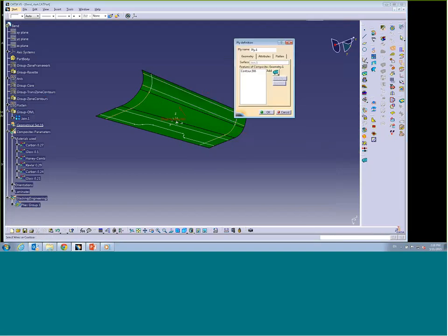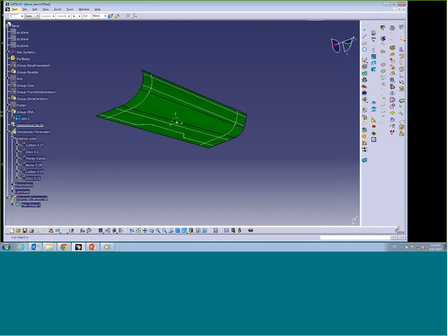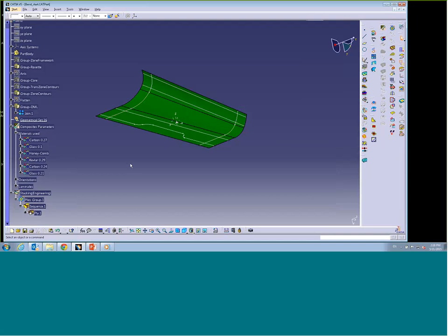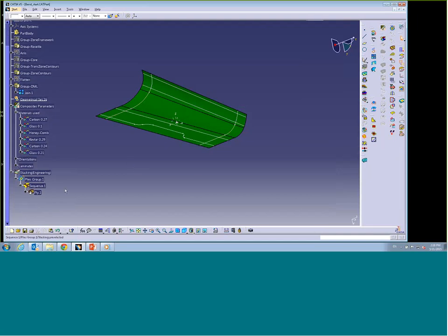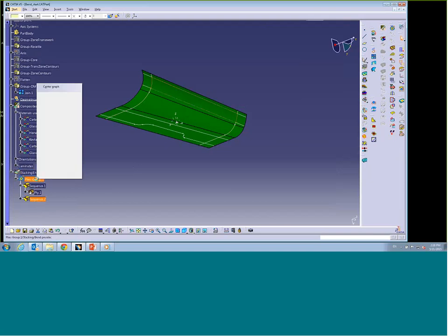Okay, that's my first ply. Attributes. Which material I want to use? Well, I want to use, let's say, this fella. Direction, 0 degree, and hit OK. So what I ended up with, I actually created the first ply. So at this point, I can use copy and paste, and let me copy and paste it several times. I'll just copy and paste it a few times.